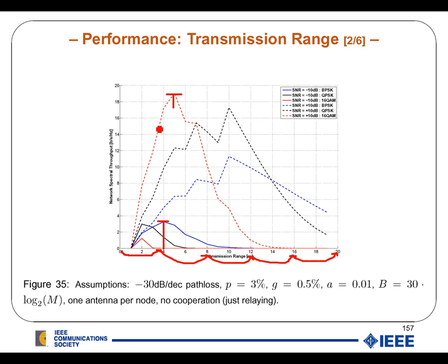So therefore it is better now to switch to shorter packets, minimizing these collisions at the medium access control, and we see that using 16 QAM and a transmission range of 5 meters, therefore reaching the destination in 4 hops, would yield the optimum end-to-end spectral throughput.